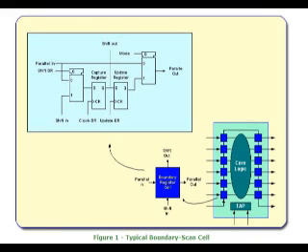Figure 1 depicts the main elements of a boundary scan cell. By allowing direct access to nets, boundary scan eliminates the need for a large number of test vectors, which are normally needed to properly initialize sequential logic. Tens or hundreds of vectors may do the job that had previously required thousands of vectors. Potential benefits realized from the use of boundary scan are shorter test times, higher test coverage, increased diagnostic capability, and lower capital equipment cost. Typical boundary scan cell.